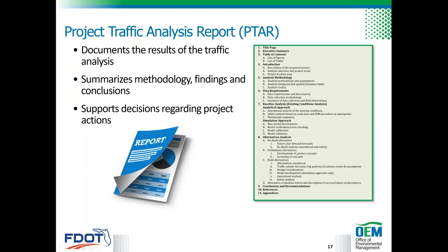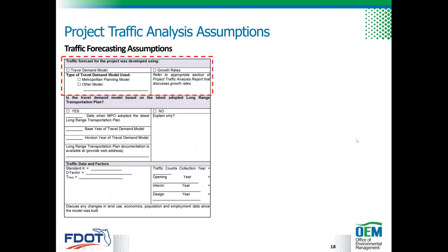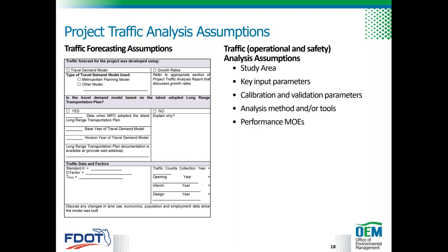And very important also, the PTAR is one of the reports that is signed and sealed by a professional engineer registered in Florida. Right, so some of the traffic forecasting assumptions. The PTAR must be reviewed and checked for quality and for reasonableness of the results. The review of reasonableness of traffic projections should include examining and comparing observed traffic and historical trends, proposed roadway and transit network improvements, and land use projections.